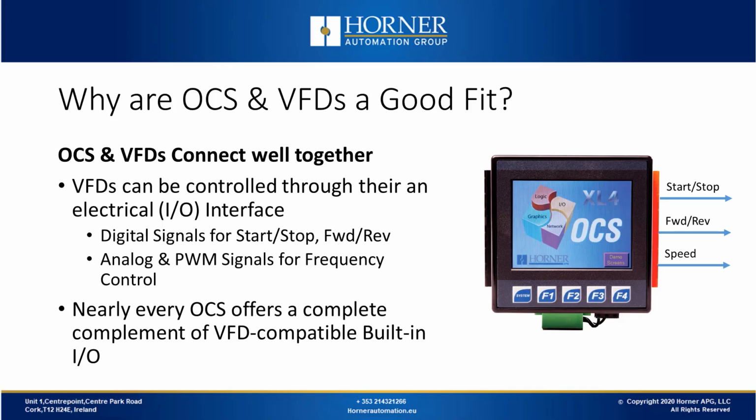Now let's talk about connectivity between the OCS and VFDs. There are a variety of ways that you can control a VFD. The most common, outside of manually, is using I/O signals connected to the terminal block of the drive to start, stop, change direction, etc. The OCS has all these signals built in. We've got more than a dozen models that all have enough I/O built in to comfortably control one or more variable frequency drives with I/O alone.